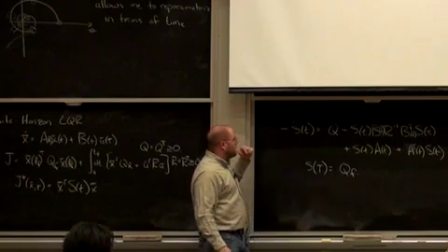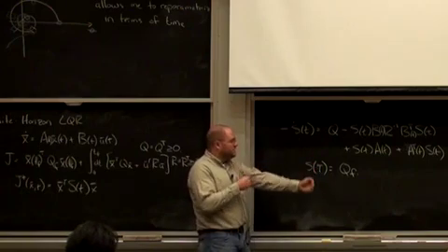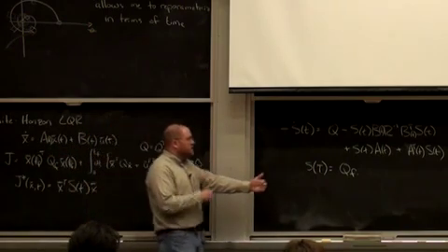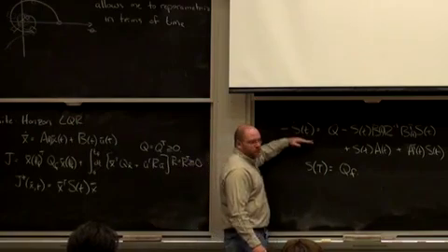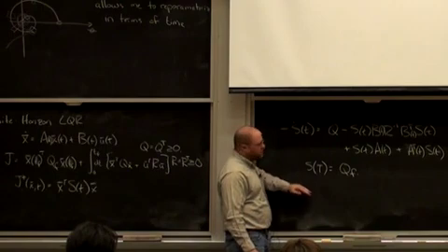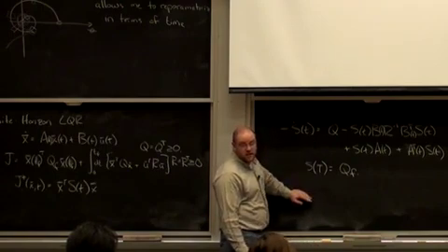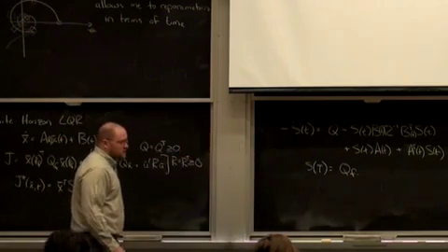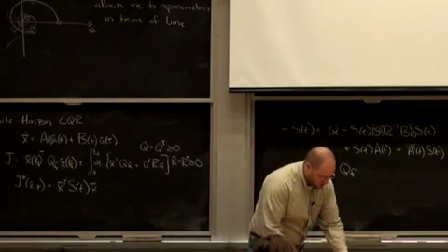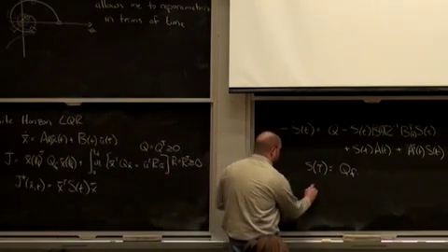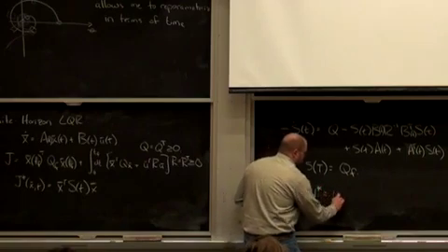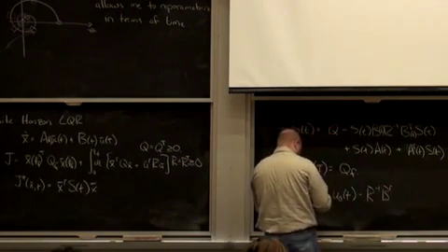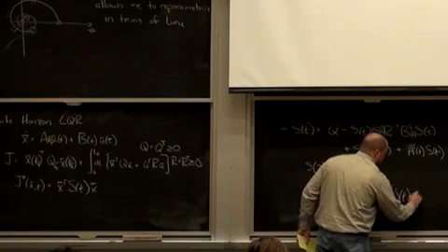Okay? In the finite horizon time, even the LTI case, which is the A and B do not depend on time, the linear time invariant case, I still had to integrate back this Riccati equation in order to get my LQR controller. Okay? It's no more expensive to do the same thing in the linear time varying feedback case. And the resulting controller is U star is my nominal controller minus my R inverse B transpose S of t x bar.